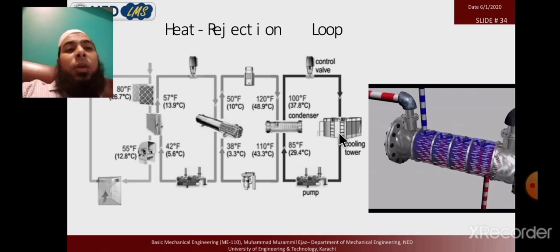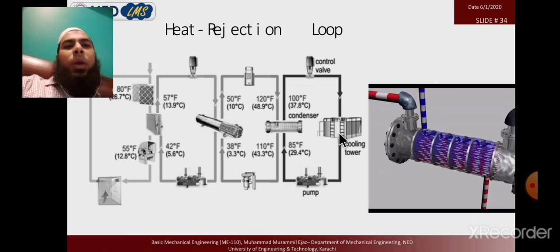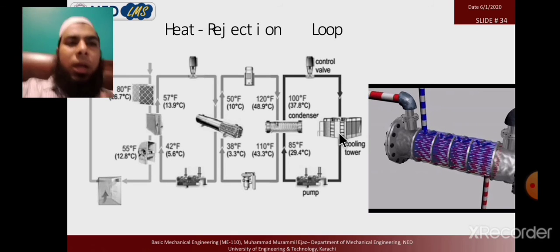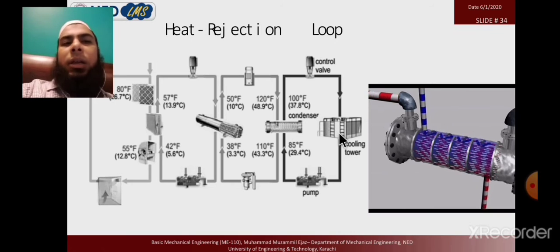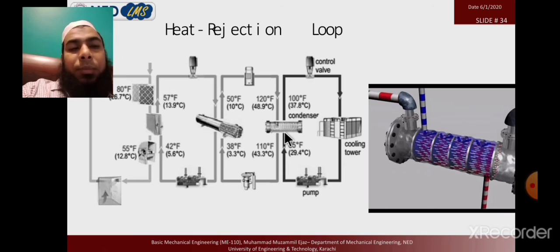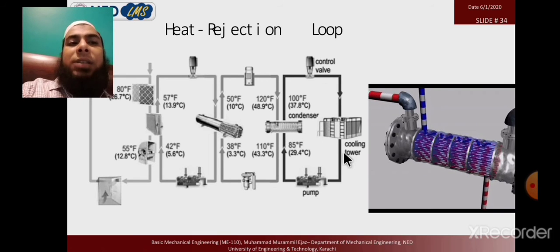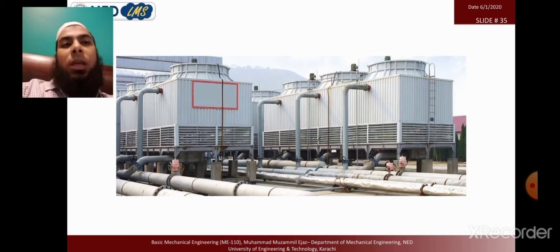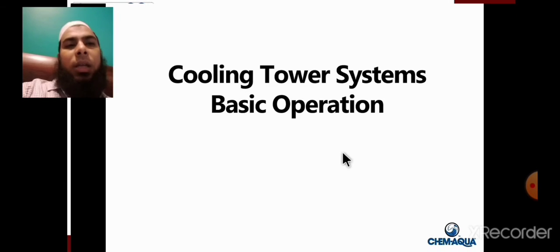So in the cooling tower system we have two advantages. In an air cooled chiller, the heat is directly rejected into the environment air. If the environment air temperature is like 40 or 35, we need very high blowers that need to reject heat from the condenser. But in the cooling tower circuit we absorb the heat and reject the heat into the environment in two ways.